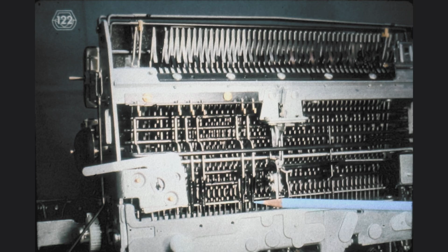Now check your machine for full latch engagement with the positive latch bail if your machine is a newer model, or 0.25 mm underlap of the selector latches with a positive latch bail if it is an older one. Be sure to also check for minimum loss of motion if your machine is a recent model.